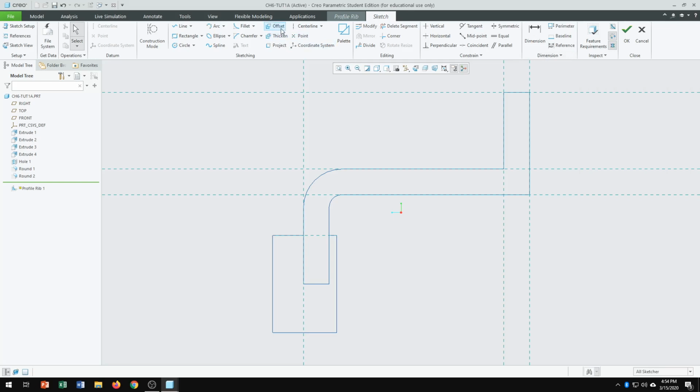I'm going to be using offset quickly, and if the arrow is pointed downward, you just enter -10 as offset, because we want the line above this line here. In some situations, I've seen that the arrow is pointed upward, then don't enter -10, just enter 10 in the direction of the arrow. Click on the curve, and then you enter 10.